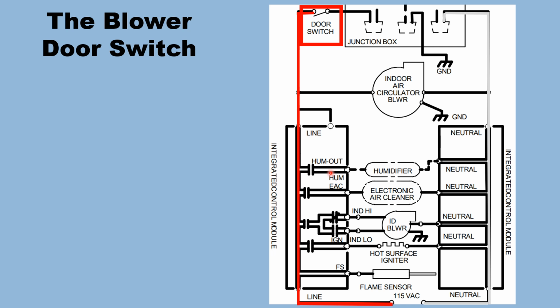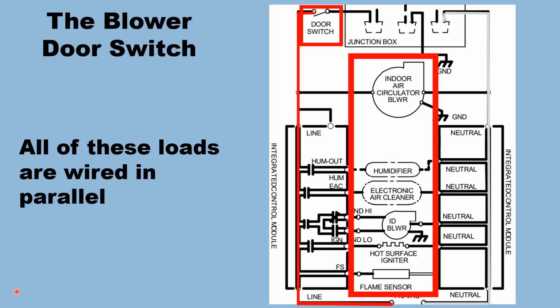And they're series parallel circuits, as I told you, because a series parallel circuit has the parallel power, but it has to have a switch in series with each thing, because something's got to control when that's coming on and when that's not coming on. Because there's all our loads and they're all in parallel, but you notice there's switches to control them also.